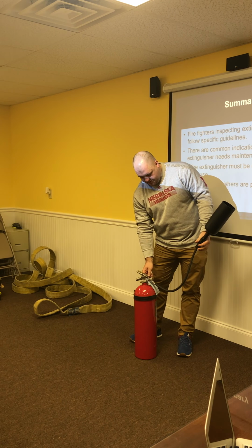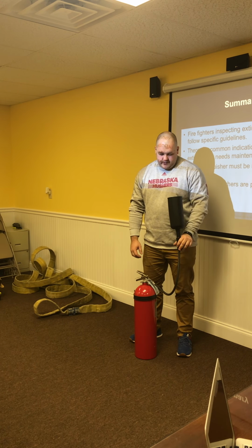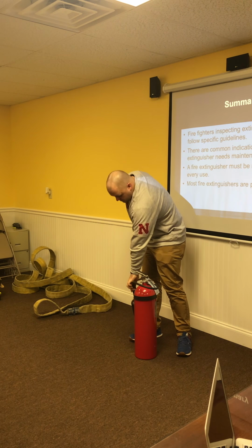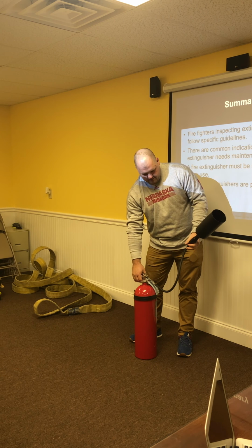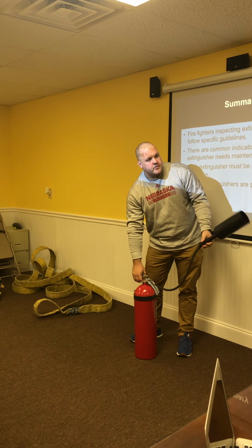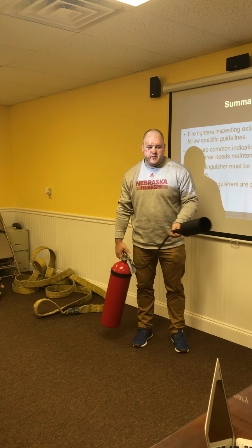He's just going to simulate everything. He's going to remove the horn from the nozzle where it was on the side of the extinguisher. He gives the trigger a quick squeeze to ensure the extinguisher operates and discharges properly. Okay, he approaches the fire with an exit behind him.